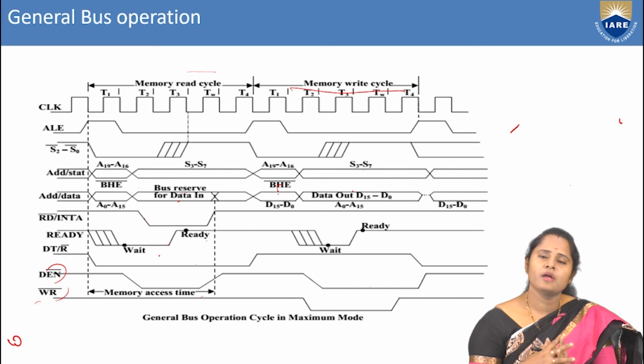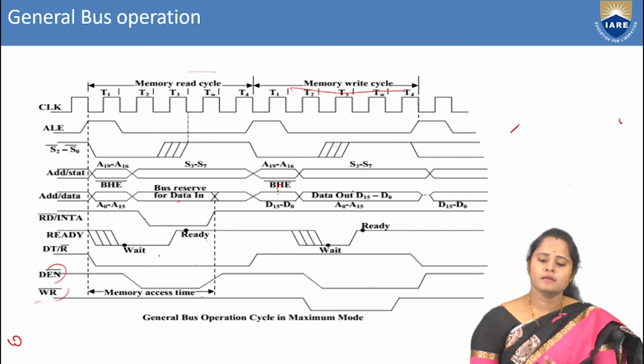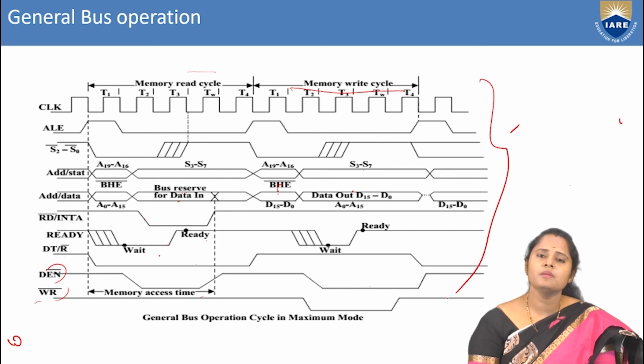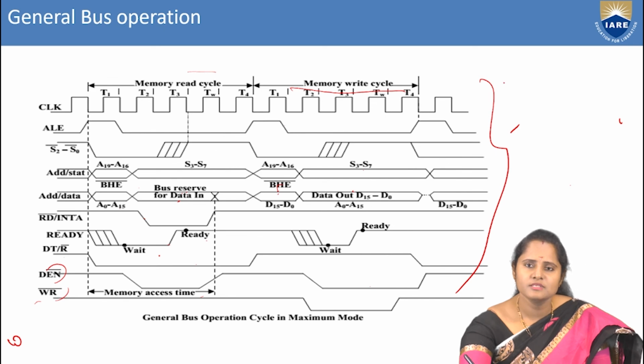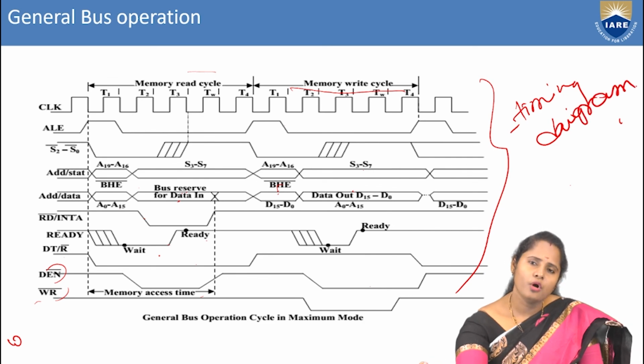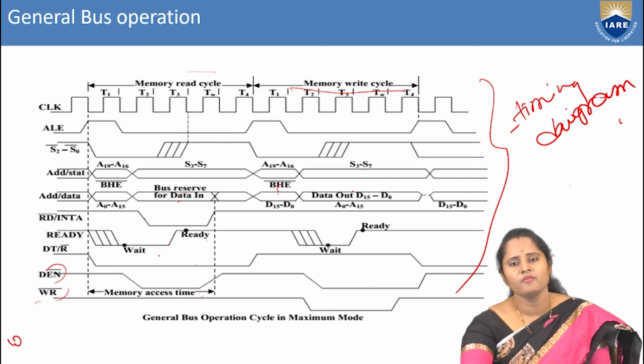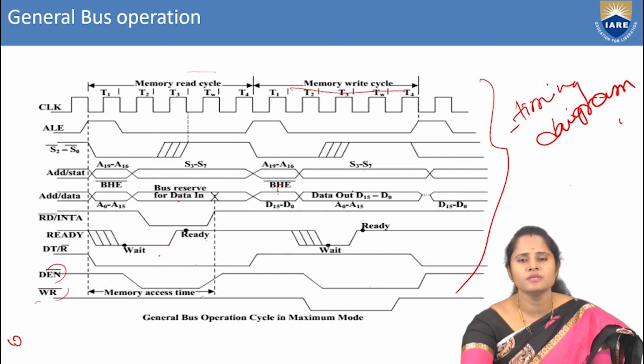how the pins are made, whether high or low. This is indicated by this timing diagram. So a simple bus operation can be understood by this timing diagram. It shows at what time period. The number of clock pulses required for one read and write operation is 5. That includes T1, T2, T3, and a wait signal with T4. Wait indicates that if any of the processors is not synchronized in the proper way, we need to wait. So that is why a TW is included.